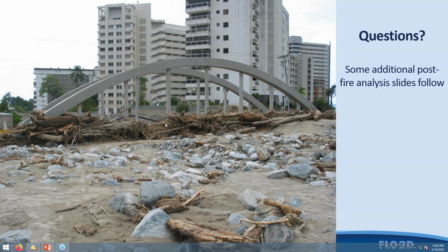How should we choose if the shape of the hydrograph and maximum discharge varies a lot in the range of CV equal to 20 to 35%? It does, and it's going to. The only thing that I would do is to play with it and try a number of different scenarios. You will see the behavior change if you rebulk it. You may even see the model generate some surging in the recessional limb. And if it does, that's a clear indication that there should maybe be a little bit more variability in the concentration by volume in the inflow hydrograph.